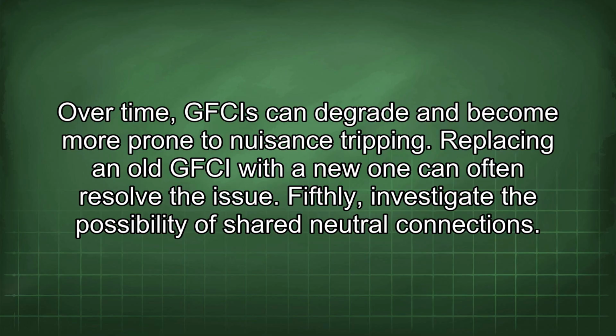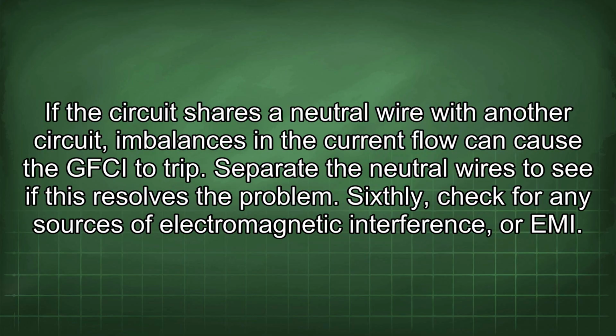Fifthly, investigate the possibility of shared neutral connections. If the circuit shares a neutral wire with another circuit, imbalances in the current flow can cause the GFCI to trip. Separate the neutral wires to see if this resolves the problem.